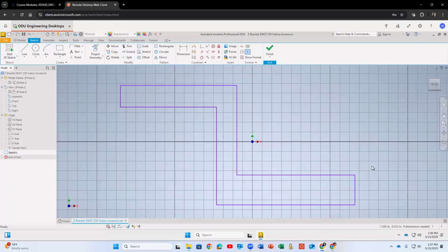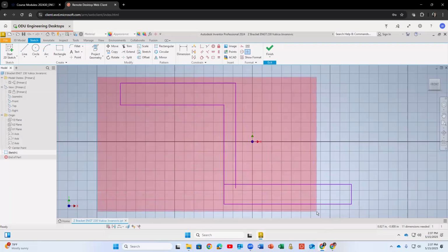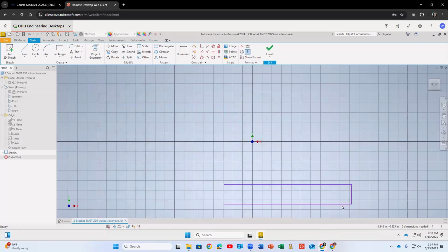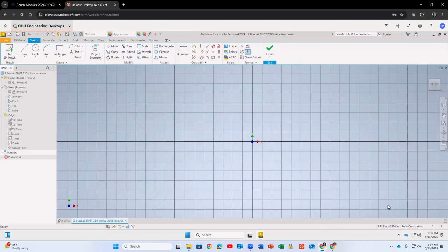And the thing is, what I really like to do before I start drawing the whole thing, look, I can just select from left to right. If you select from left to right, everything in the rectangular shape is something you can delete. So look, like this one, I can delete that. But if you select from right to left, everything that you're touching is something you can delete, even if you didn't select the whole thing inside. So look, if I select, you see what's missing. So, there's a difference if you select from left to right or right to left. So you see, I select everything and I want to delete that.